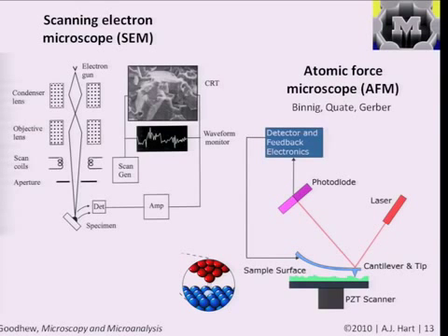And then another really pioneering, and in fact Nobel Prize winning, characterization technique is what's called the atomic force microscope, a variant upon the scanning tunneling microscope that gave the picture of the ring of atoms on the previous slide. And here you're imaging physically. You're taking a very, very sharp tip, what looks like a little stylus or a little finger, running across the surface. And the idealization is having a tip that's atomically sharp running across the surface, and you're creating a picture by physically scanning.